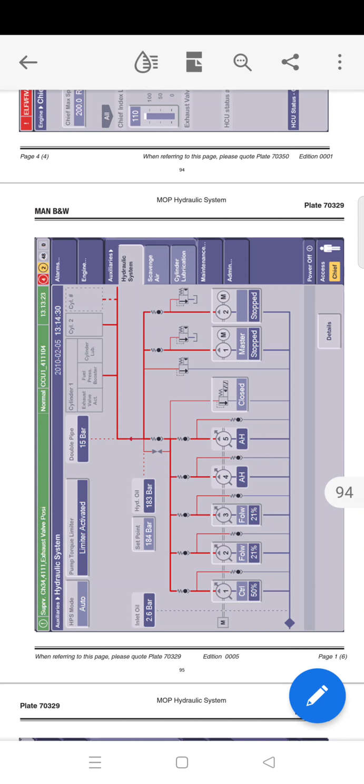The screen shows a simple schematic drawing of the hydraulic system. The screen shows from 3 to 5 engine driven pumps depending on the engine layout, and 2 electrically driven startup pumps. A bypass valve from pump pressure side to suction side is also shown, so you can see it. The following buttons can also be activated directly from the screen in chief level. So what are those? We can see the SPS mode, that is hydraulic power supply mode, the pump torque limiter, the set point, and the bypass.